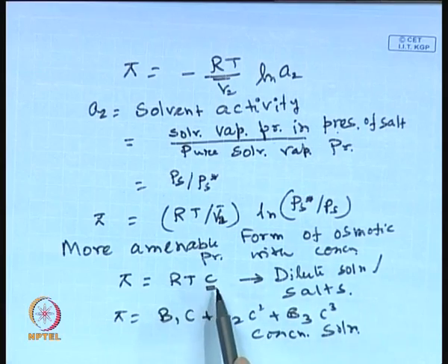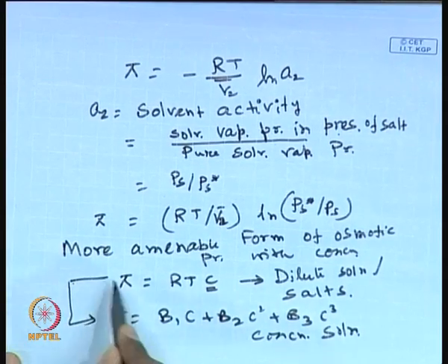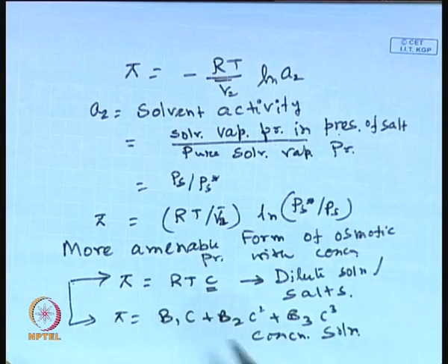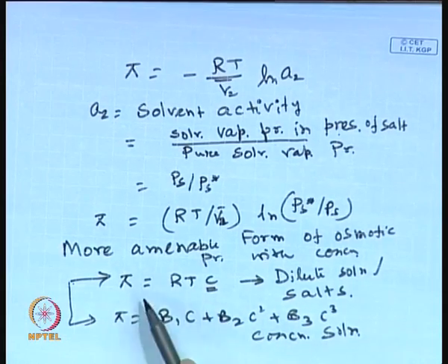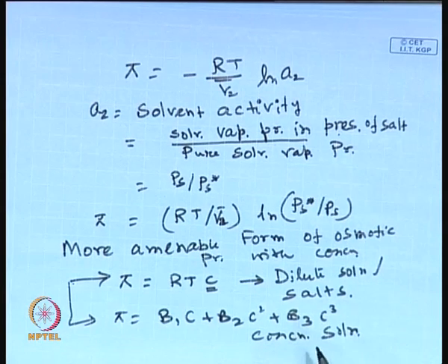And this corroborates the fact that osmotic pressure is a colligative property and it is a function of concentration. We have discussed in detail, probably in the last class, the range of applicability of the linear relationship of pi versus C like RTC, and a nonlinear relationship as a polynomial function of concentration. Now, once we identified that osmotic pressure becomes a vital parameter in reverse osmosis, where the pore size is extremely small, the smallest possible pore size in membrane based separation processes.